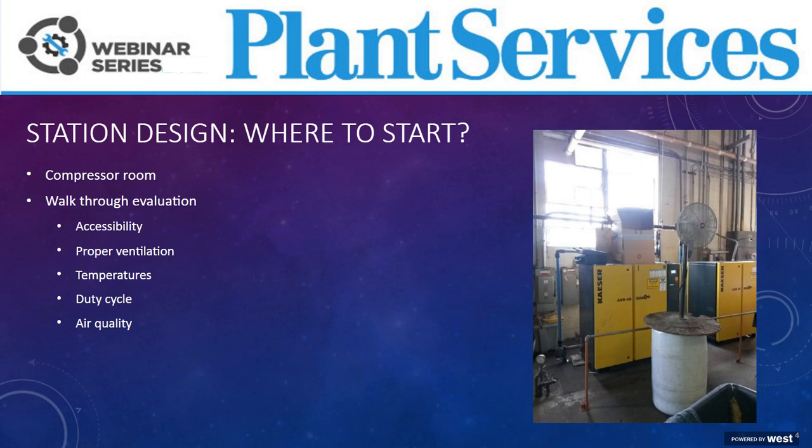Looking at equipment on paper, everything may be fine, but what you necessarily can't see on paper is whether you have access to the compressors. Is it a hot, dirty, dusty environment in the compressor room? What's the duty cycle your compressors actually have? You'll also see that we listed air quality among the items that you want to review during a walkthrough. When you're walking through the compressor room, check if there's water in the receiver tanks.